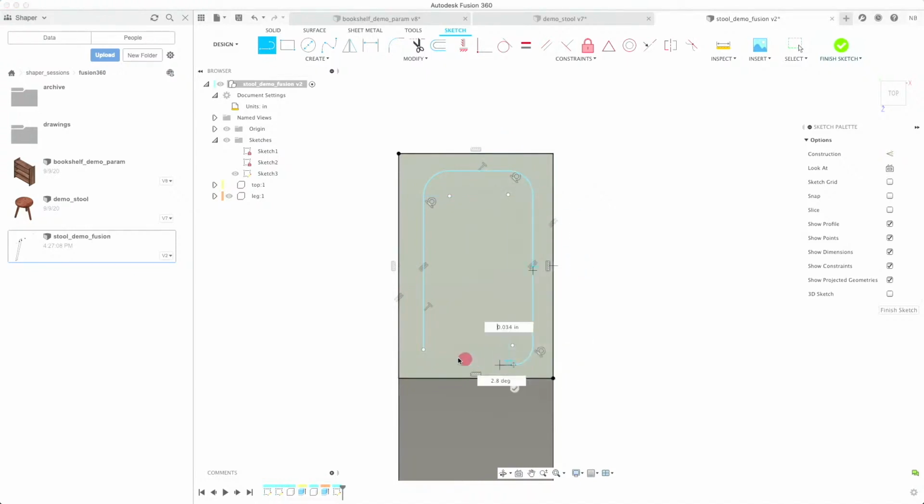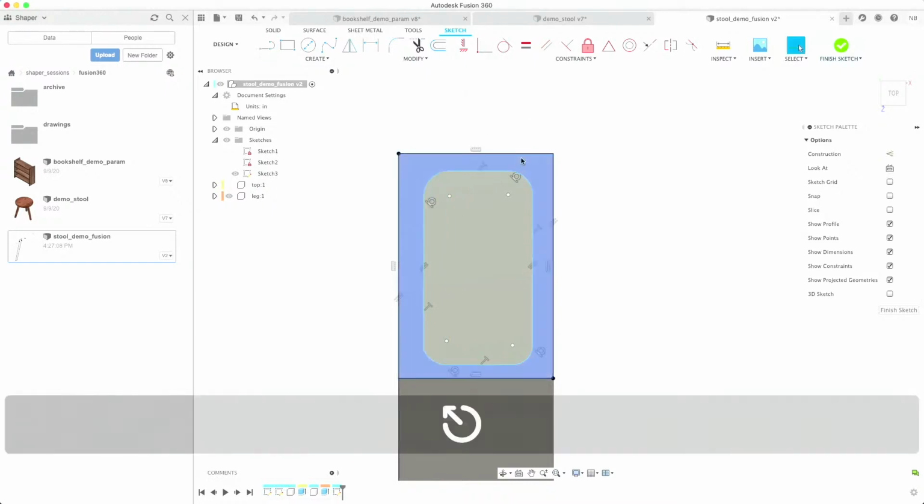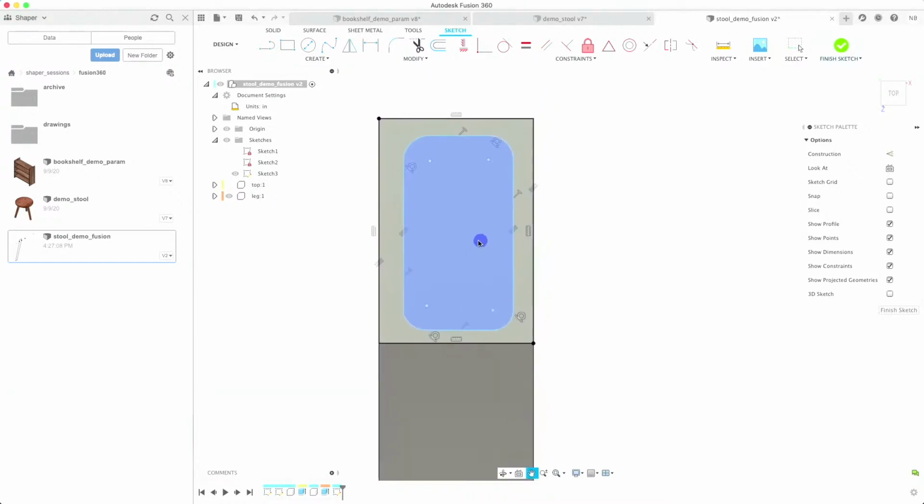So we're just making these round so that the tenon has got round profiles, so that when we make the matching mortise, we can cut that with a router. Obviously, we're going to have to be considerate about the router bit's diameter on how we size these radiuses. Okay, so a couple things. First thing is that neat sort of trick with the line tool. It makes a tangent relationship, so again, a constraint between only the line that you started with, not the line that you ended with automatically.